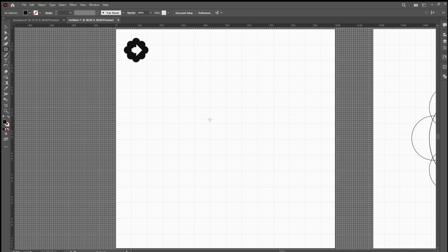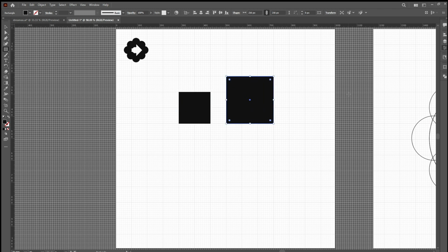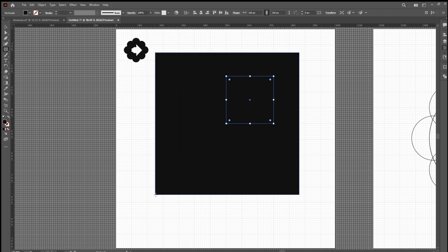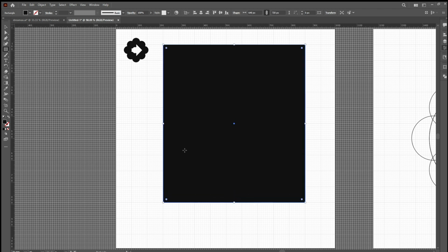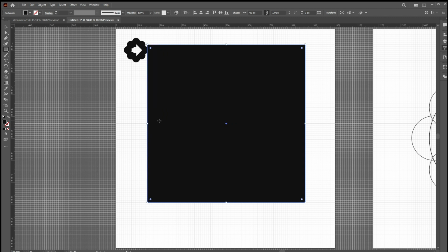All right, so if I want to draw a square, if I do it this way, in order for me to know that this is correct, I can come to the properties panel and look at the width and height over here, and you'd see that they are equal. Normally you will not be able to do this. You can see they are equal. Whichever way I want to draw it, it's going to be definitely equal if I follow the grids. I have to bring this one down, bring this downwards, and then take this one to the left, and you can see that's equal, 720 by 720.